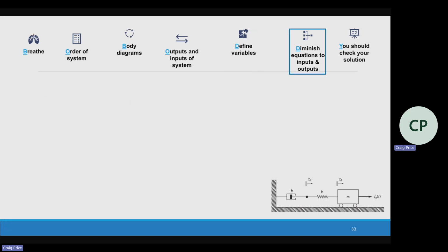So now we get to the mass: sum of forces equals m z double dot. Which z is this, by the way? Because that does matter. What acceleration are we tracking if I'm looking at the mass? Yes, z1. So on my free body diagram, I have a positive input force. I've got a negative spring force. So we put that definition in.